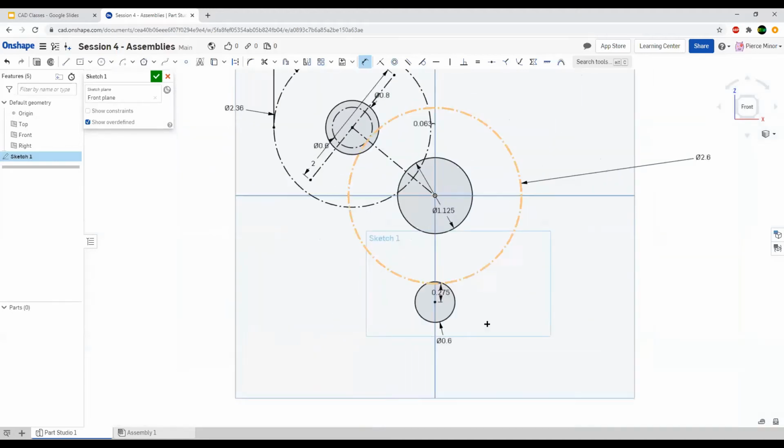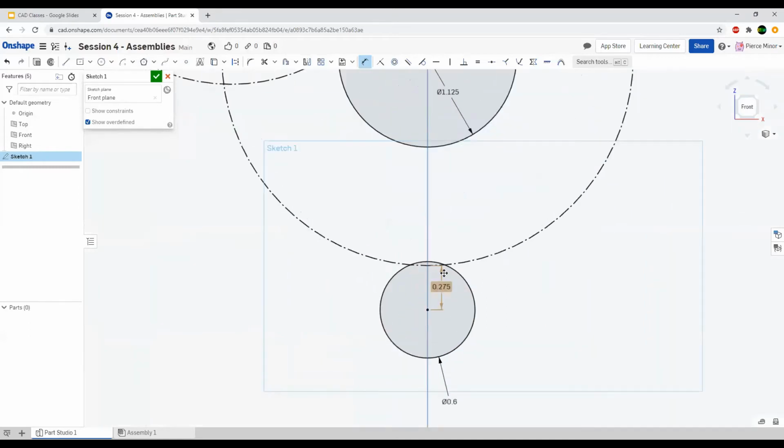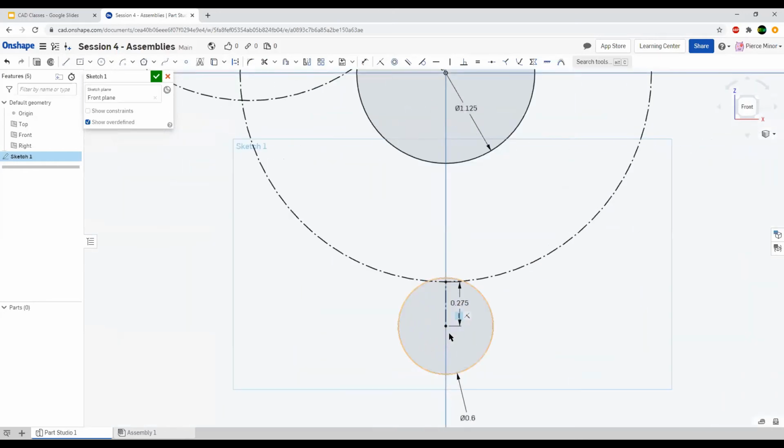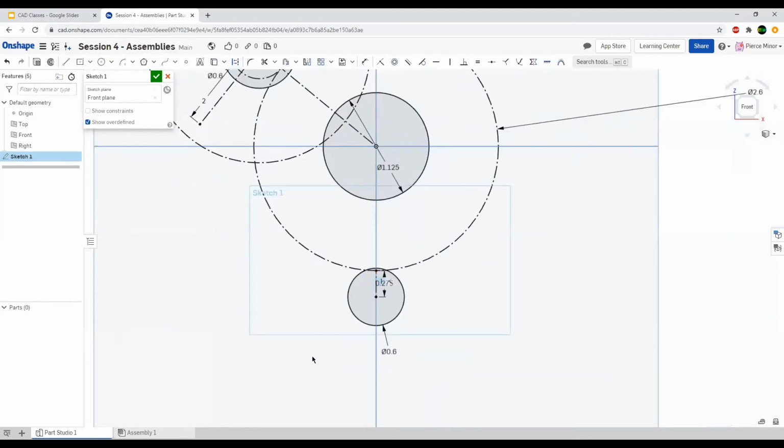Also, this is one of the downsides of making weird numbers like this. If it's going to be something that you're going to use somewhere else, I highly suggest drawing a construction line, and I'm actually going to do that right now, so that later, if you have to use that same number and it has to be the same from there to there, you could just very quickly copy that line instead of changing every single reference to that number every time. It gets complicated after a while.